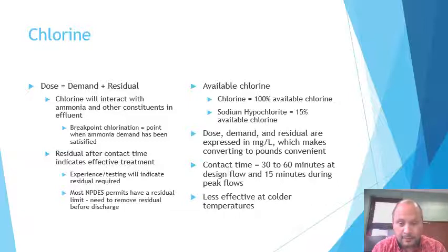So again, dosage equals demand plus residual. Those are expressed in milligrams per liter, which makes for easy pounds formula problems to be included on exams. Remember your contact time for disinfection, and also chlorine being less effective in colder water temperatures.